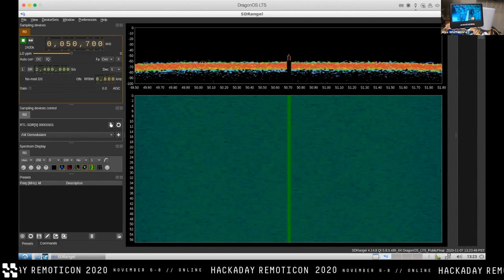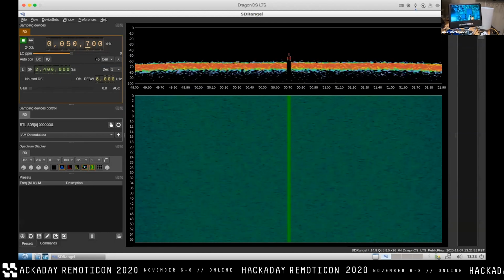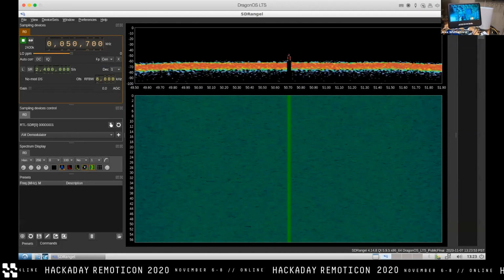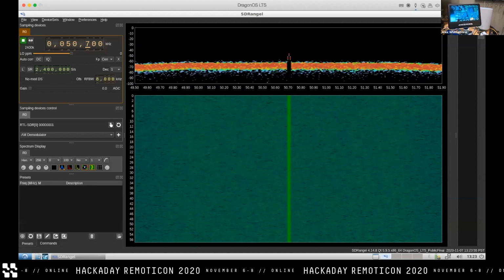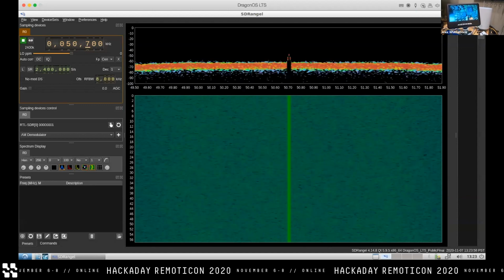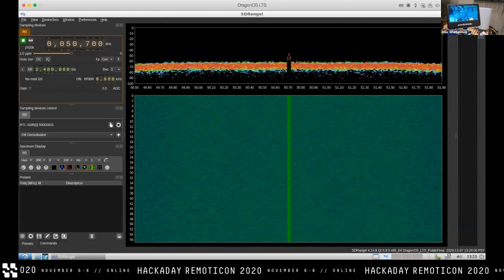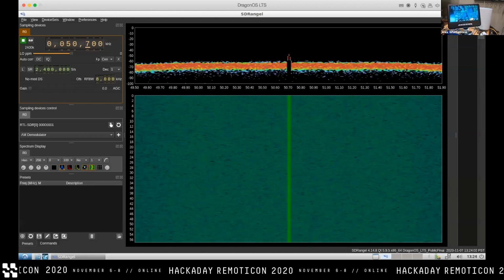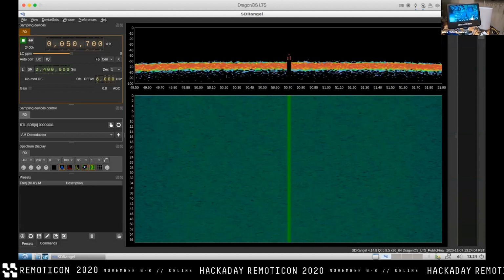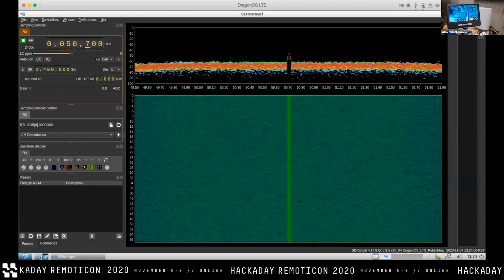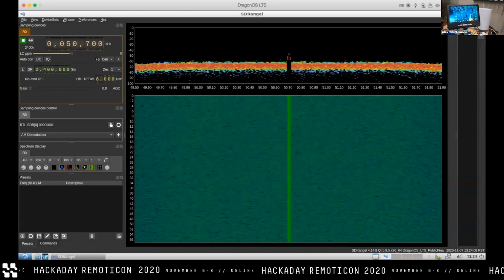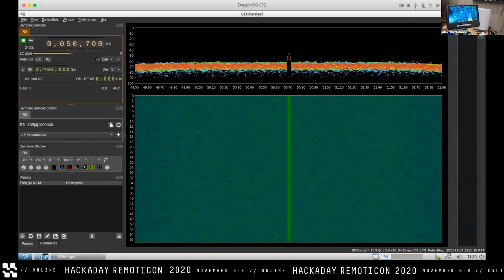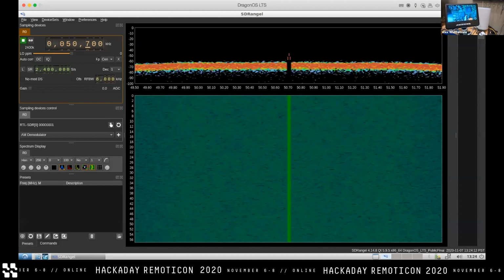probably coupling noise onto the IO bank supply rail because we're driving a relatively low impedance device at a ludicrously high frequency. This thing looks a bit like a capacitor as well as a resistor, as well as a diode. So we're really probably taxing that voltage rail pretty badly, and we're seeing it in the form of supply current from these capacitors trying to keep that rail stable.